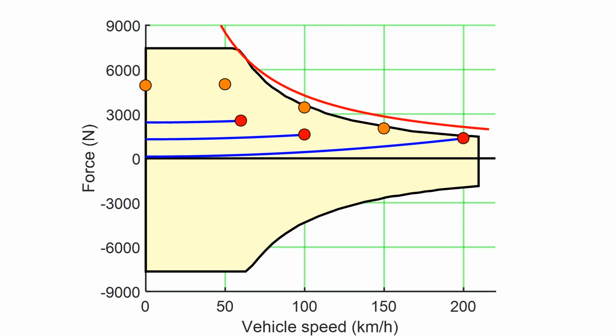The peak power is only possible to produce close to 60 km per hour. When the speed increases above 60, the maximum power of the powertrain drops, and at high speeds it's only 85 kilowatt, which is only 72% of the peak power. This is a reason why this electric powertrain easily meets the low-speed requirements, while the high-speed requirements require it to use its full capacity.